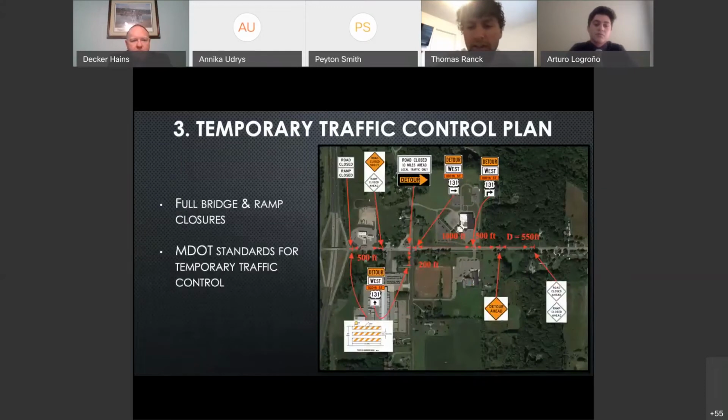Following MDOT standards for traffic control, temporary detour routes were constructed using proper signage and spacing. As we will discuss in the construction schedule later, we chose to do a full bridge road closure of 100th Street, as the detour routing to US 131 would have little impedance on the public, since there is entry to US 131 located just over a mile to the north on 84th Street.